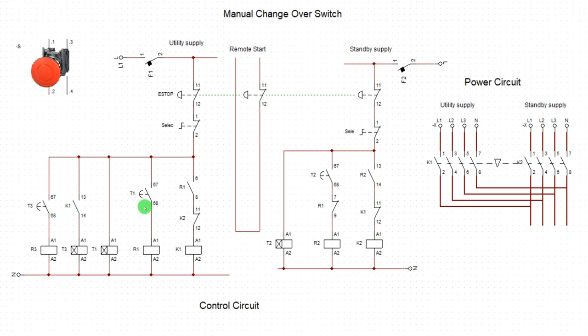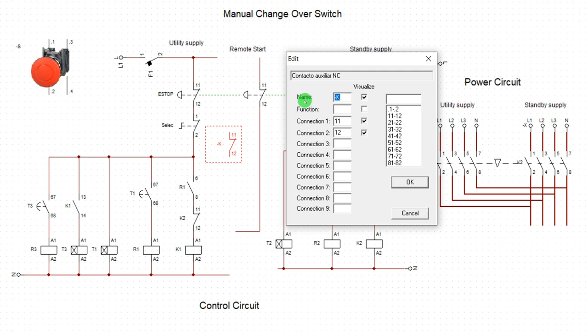All right, now, because I don't want to rely on the cooldown duration of the panel before shutting down, I want to introduce my own. The contact of this particular relay, we are going to insert it here. It's going to be normally closed. I told you, when you open, the genset shuts down. The terminal can be whatever you find on the terminal.